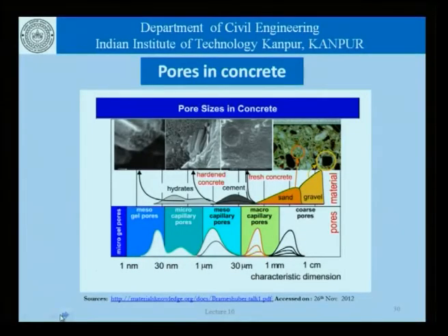This is yet another picture showing the different pores, different terminologies. There are coarse pores, there are macrocapillary pores, mesocapillary pores, microcapillary pores, mesogel pores, and microgel pores. So, what it really shows is that the porosity or the pores in concrete have attracted the attention of a lot of researchers, and they have used different tools to examine these pores, determine their sizes, try to understand their genesis and their properties, and try to give them names.